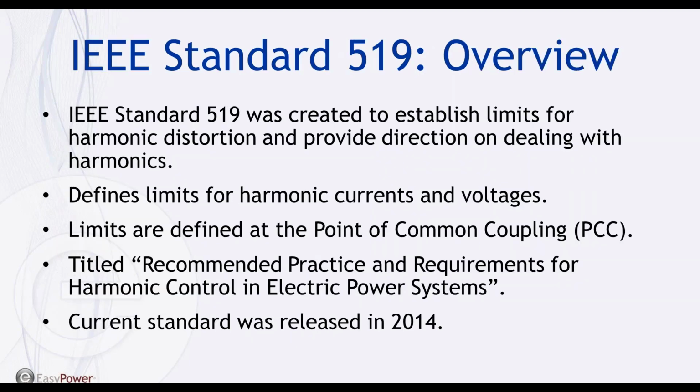So IEEE standard 519 was created to establish limits for harmonic distortion and provide direction on dealing with harmonics. It was intended to provide direction on dealing with harmonics introduced by static power converters and other nonlinear type loads. The standard was written to establish goals for the design of electrical systems with both linear and nonlinear loads. It is presented as a guideline for power system design when nonlinear loads are present and assumes steady state operation.